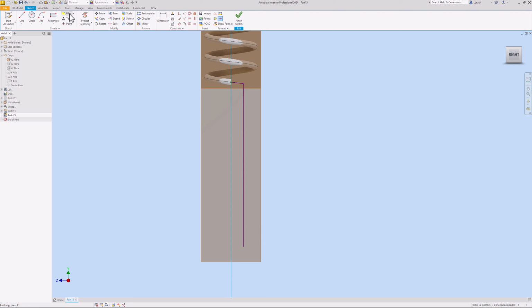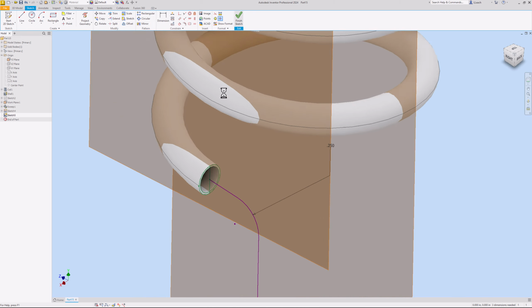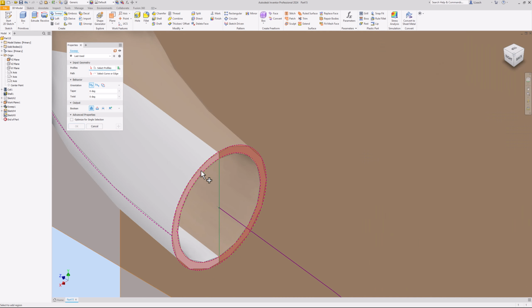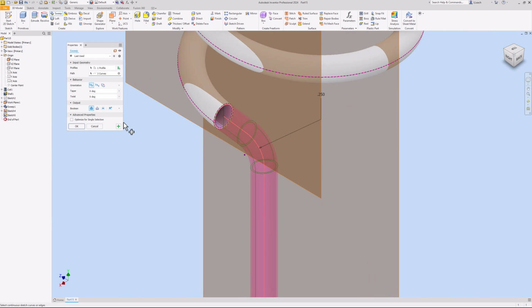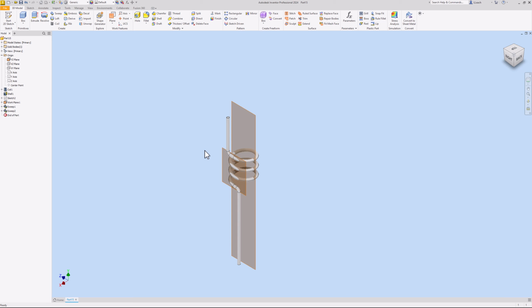And again, we're going to fillet this. I already have it at 0.25, so I want to fillet this and this. And then finish my sketch. I'm not going to revolve, I'm going to sweep. I want to sweep this ring part along this path that we made. And we're going to hit OK. So there is our straw, nice and neat.